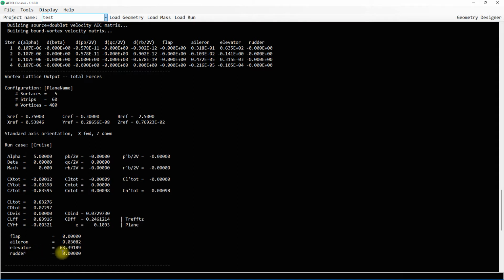And the rudder is not deflected at all. So with this, what we can see is that the ailerons are going to be used for balancing the roll, which is about the x-axis, the elevators about the y-axis or pitch, and the rudder about the z-axis.